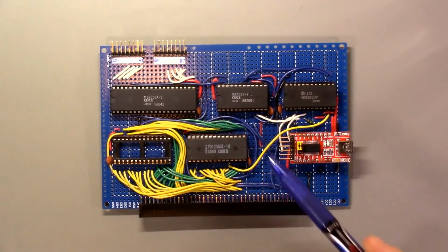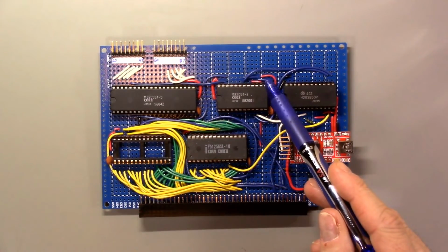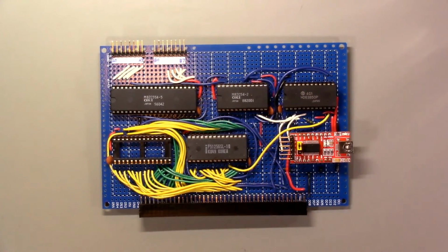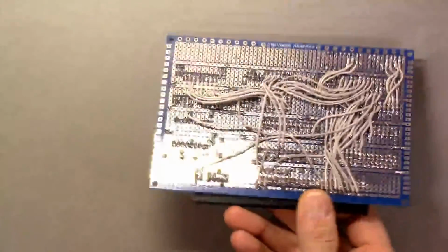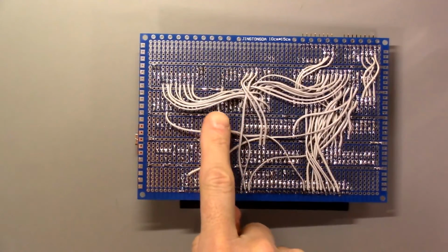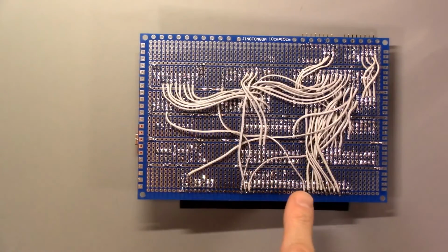All right, so here is the peripheral module, and pin 13 on the 82C54 is the output for Unit 1. If we look on the back, essentially what we have here is a wire that goes from that pin onto an appropriate, currently unused backplane signal, and that will take that timer interrupt pulse and make it available to the interrupt controller.